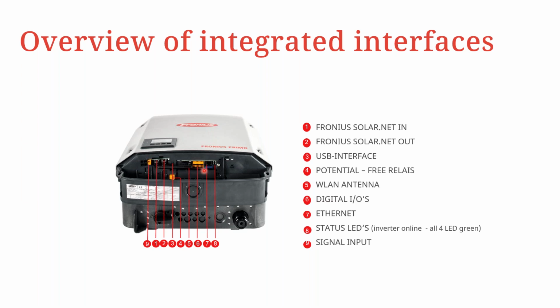So here we just have to take note that when you have the sensor card integrated, you're going to do the connection of the cabling from the sensors within the same data communication area as where you do the communication, for instance, for Modbus connection to the smart meter.